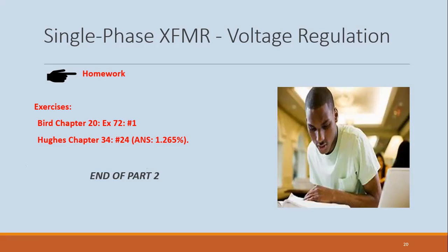What we did in the test was just turn off one of the switches, so one of the bulbs would have gone out. That circuit would have been described as an open delta, but the supply voltages haven't changed, neither the phase angle nor the magnitude.